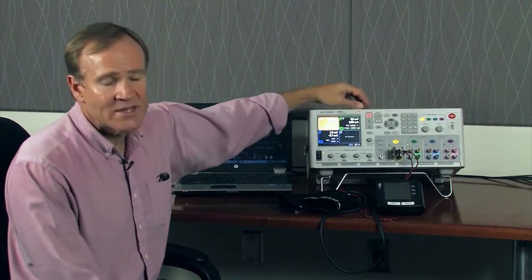Channel 1 is connected to an SMU, or a Source Measurement Unit. The unique thing about this Source Measurement Unit is that it has 4 current ranges. 3 of those you can actually switch between seamlessly. And this is a patented technique that we have that gives you 28 bits of dynamic range. This enables you to measure the sleep currents at 10 microamps and the execution or operating currents, for example, when you're transmitting RF at, say, hundreds of milliamps.